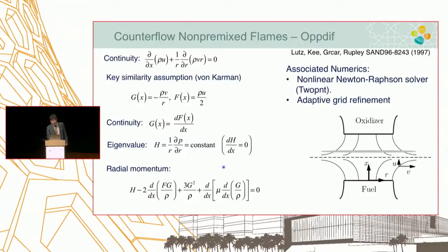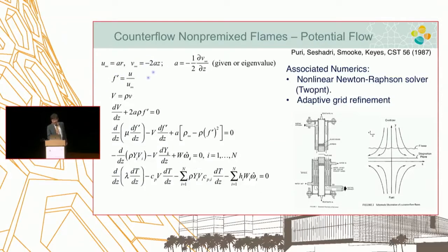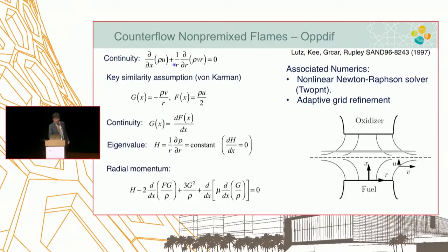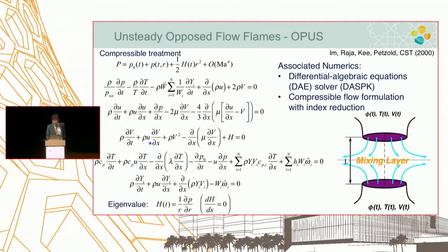And the effective strain rate, the one downside is that you have to compute it afterwards. So there's a trade-off. One way allows a very nice systematic parametric sweep by changing A over a certain range of conditions, but the other one is easier to compare against the experiment directly. That's the more commonly used today, because everybody running this simulation compares with the actual burner experiment.